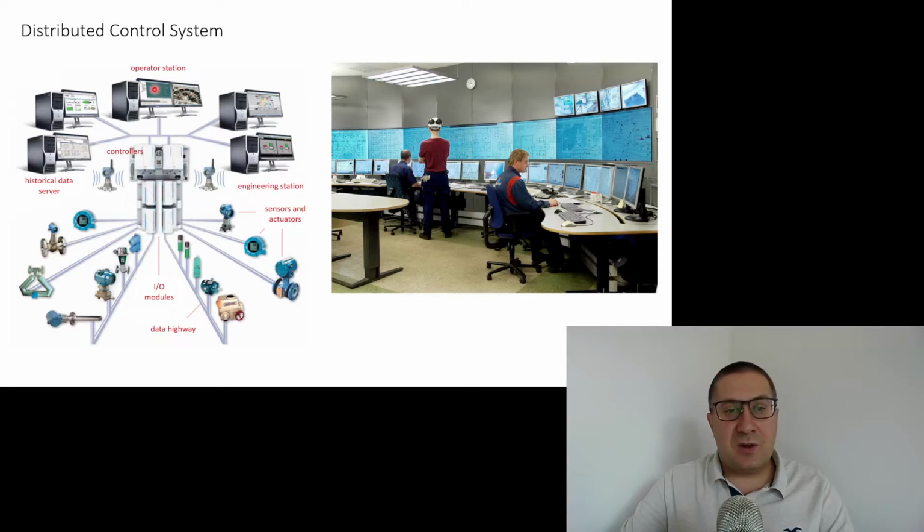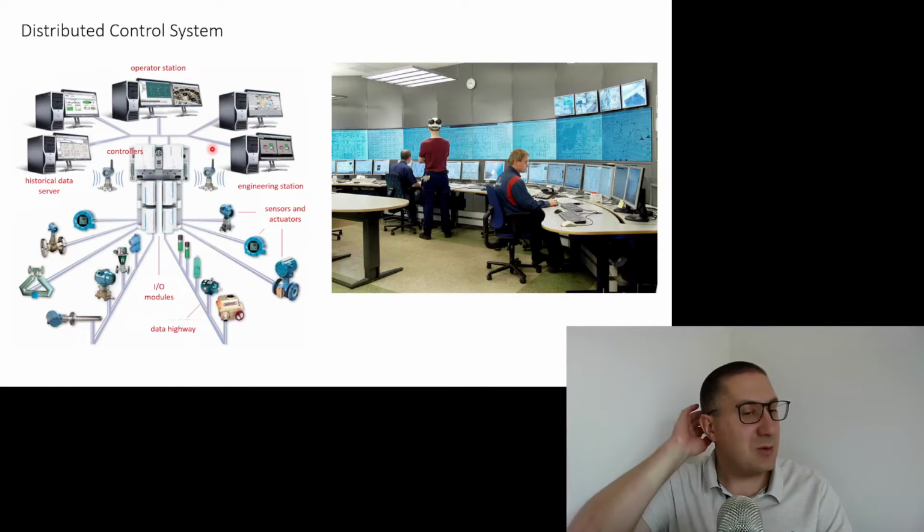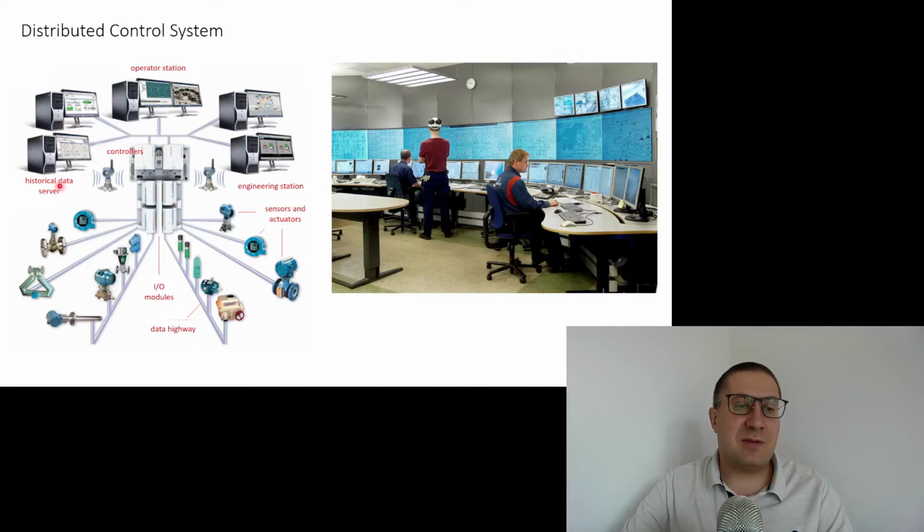All right, and of course, we will also like to read the points, so we will read them from this highway, from this network, the live data. We can also read the historical data from the historical data server if we are planning to do some identification experiments to increase the variance of the data, to check how the process responds to decision changes.